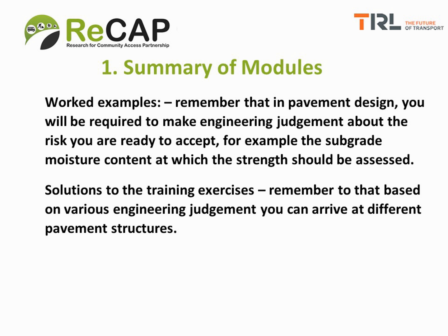Module 5 covered worked examples, and I would like you to remember that in pavement design, you will be required to make engineering judgment about the level of risk you are ready to accept. One of such is the subgrade moisture content at which the design strength of your pavement should be assessed. You as the designer will be required to decide based on the drainage conditions that you expect your pavement to be subjected to in its service life.